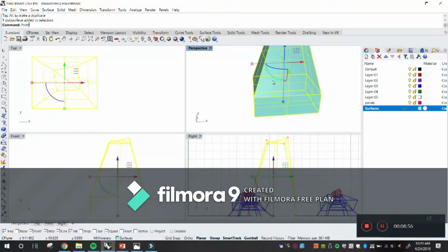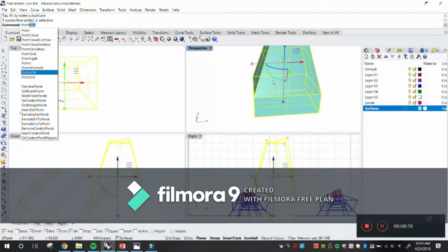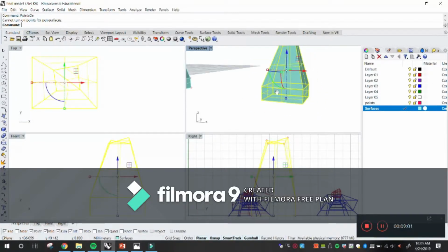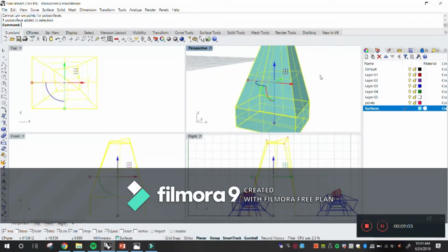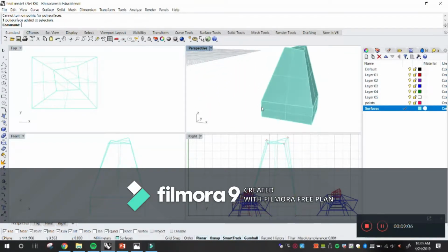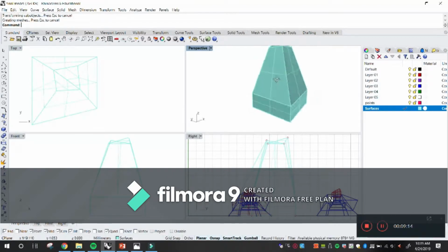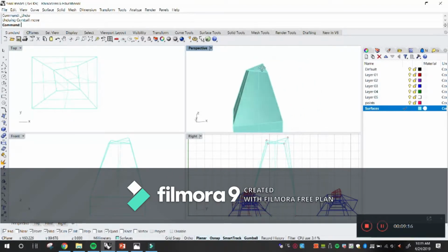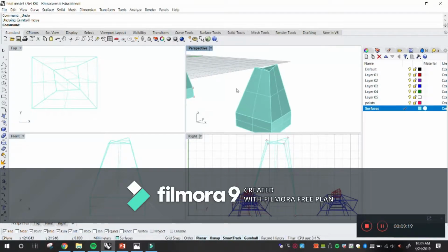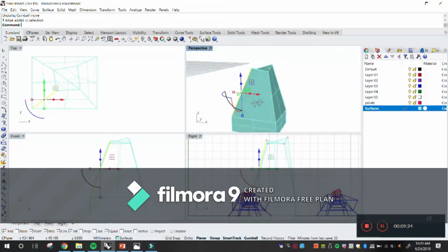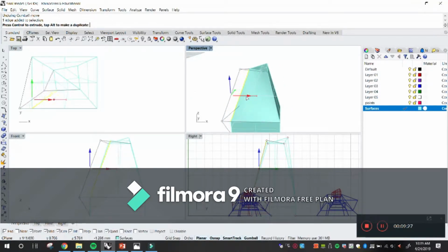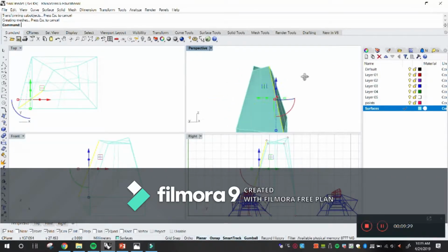Now what's neat about that, right, let's see if it's going to work right here. Let's see if I turn the points on, or if I select the object, type points on. Let's see, it doesn't really work right there, but there's this other command, right? If you hold Control Shift and then click on stuff, right? Now Bibi knows about this. You can start pulling stuff, and I'm gonna repeat that again, okay? So if you press Control Shift and you left click, that means you select something, right? You can start pushing and pulling. Make sure you drag the arrow. Make sure that you drag.